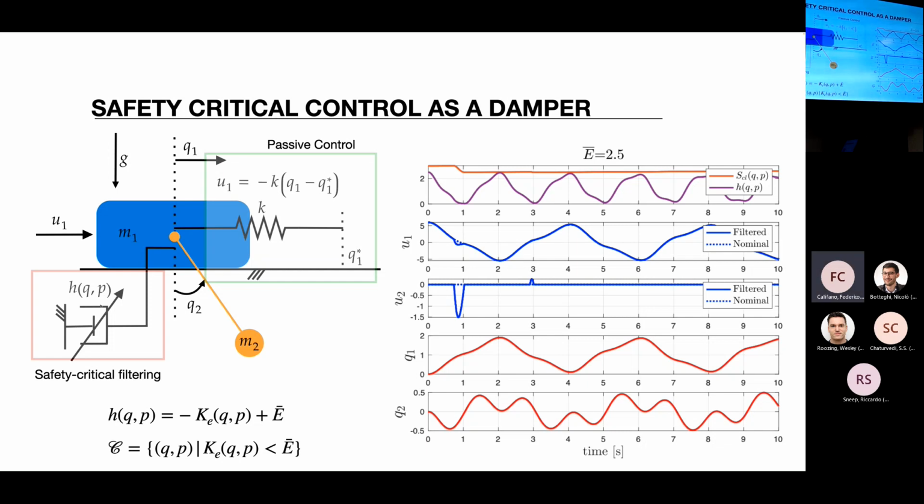Say, okay, I use a CBF which enters this class of CBFs which maintain passivity, for which I give, by the way, a necessary and sufficient condition to exist. So it's really equivalent, no? Say I want the kinetic energy to be less than a constant, say for safety reasons. Okay, then I choose this CBF, of course. This encodes the safe set that the kinetic energy is less than a constant. And I let the system evolve with more energy than the allowed one. Okay, some stored in the control spring and some in the initial kinetic energy.